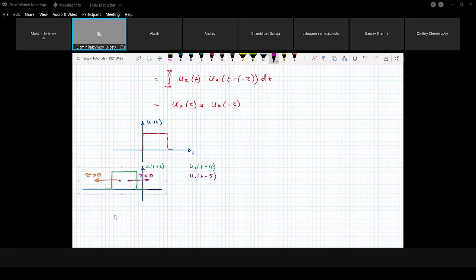What we do, we have our signal. For 0 delay, they match each other. But when we introduce delay, the second signal copy starts to move to the right or to the left, depending on the value of delay, whether it is positive or negative. And if you take a very large delay, then they don't overlap anymore. If you take, for example, 10T delay, then there is no overlap. As a result, correlation equals 0 for this specific case, because they simply do not overlap.